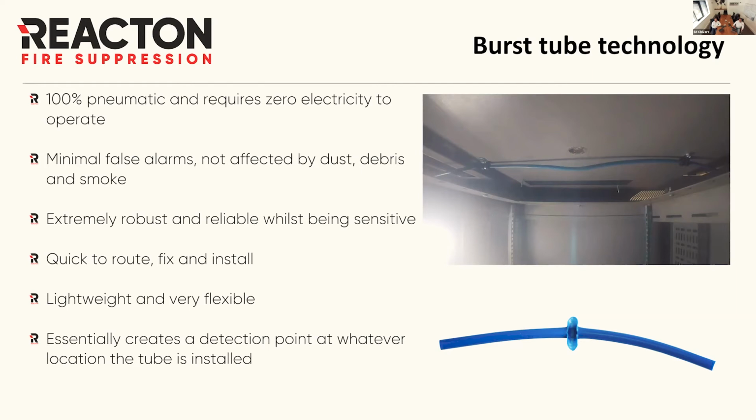It's one single moving part in the valve, and you can't not have the system go off if you release pressure in the tube. So for us, we like it not because it's a cheap or easy to engineer product. In fact, it's a lot more difficult to engineer a pressure loss system correctly so that it holds its pressure correctly over its lifespan. You don't have false activations, but the reliability is unbeatable. So that's why we like it.